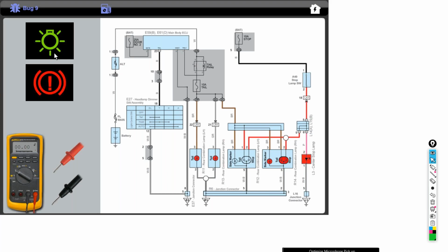But as you're covering basic diagnosis of electrical with a voltmeter, normally you go over voltage drop, and tell them you check for available voltage, and you check to verify it has a good ground. Good ground, again, 0.1 volts or less. So at this point here, we could test 12.54 volts on the stop lamp circuit, 12.56 on the tail lamp, 12.56 on the side marker. All three bulbs share a common ground and go down here.